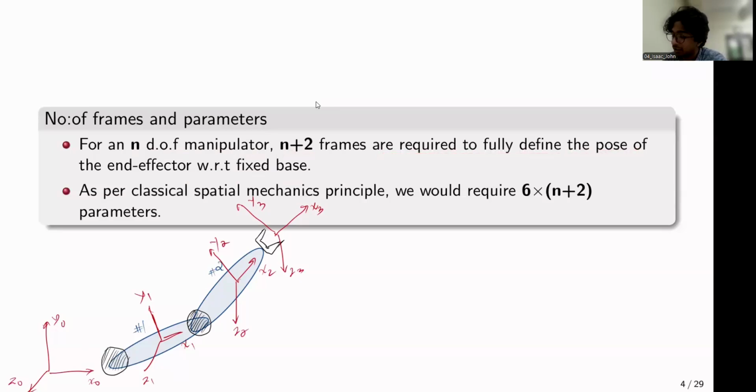So all the information that you have of this end effector point will be subsequently transferred through all the preceding frames all the way up to the base frame. It can go either in this direction. The chain of information can go in this direction. We call this inverse kinematics, or it can go in the other direction. We call this forward kinematics.